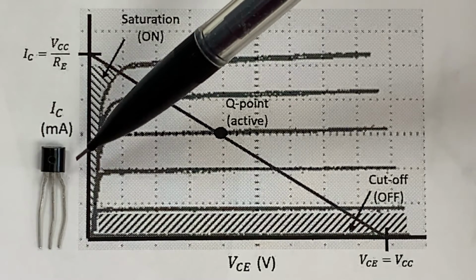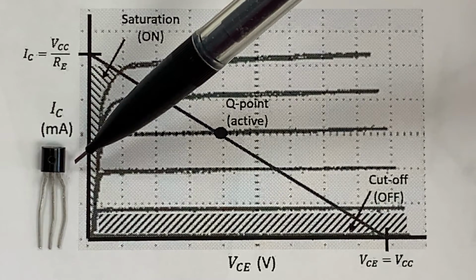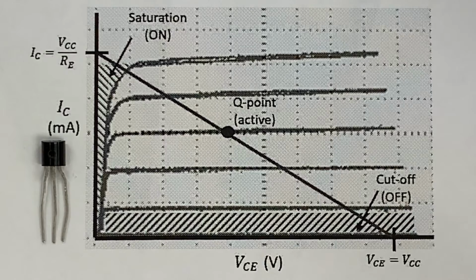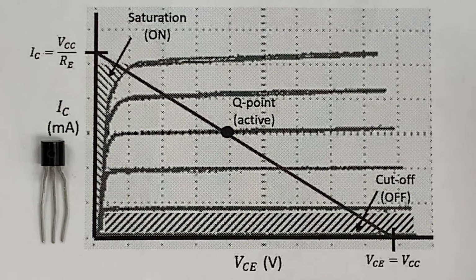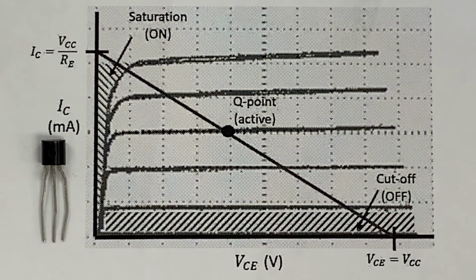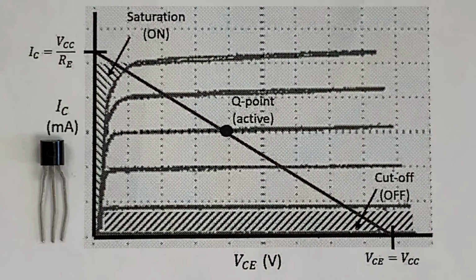We can then amplify currents or decrease currents that are given to it. Our example for part B will be the current mirror setup, which uses 2 BJTs of the same type, the same NPN transistor as we used in part A. We'll be manipulating the current by giving a high load resistance, which will provide a low current, while a low load resistance will provide a high current.